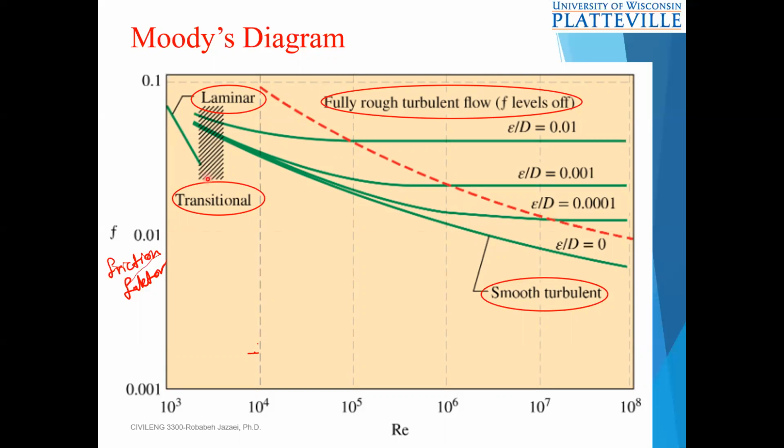It's for laminar flow. You know, for laminar flow, friction factor is 64 over Reynolds number. And now you can see why it's laminar, right? Whereas for turbulent or transitional flow, it's a curve. So we don't have to use Moody's diagram for laminar flow because it's easier to find from this equation. But for turbulent and transitional flow, it's better to use the graph, the curve.